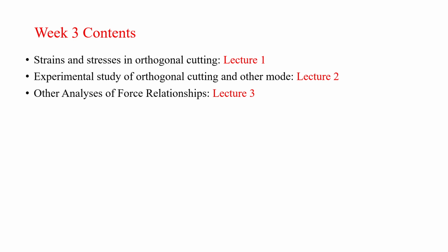Sir, in assignment 2, the value of Coulomb's coefficient came around 1.02, more than 1. Was an option there? No, it was a fill-in-the-blanks type question. Which question was it? In an orthogonal cutting, cutting force is 300 Newton, thrust force is 200 Newton, rake angle is 12 degree. Effective Coulomb's coefficient is up to.